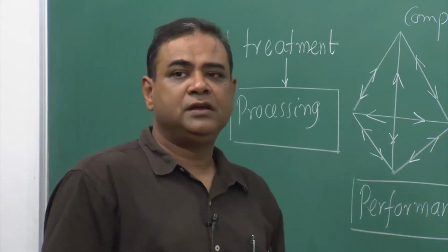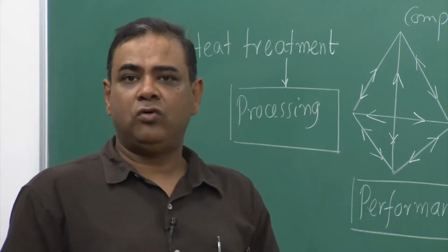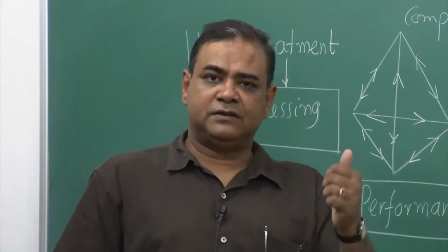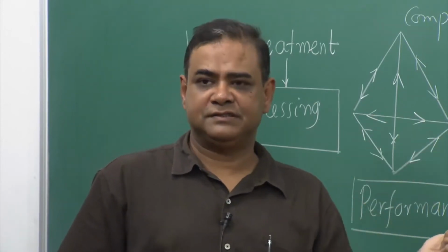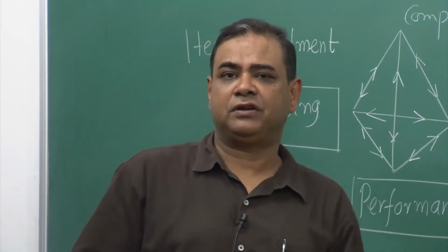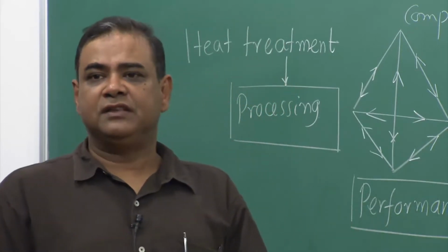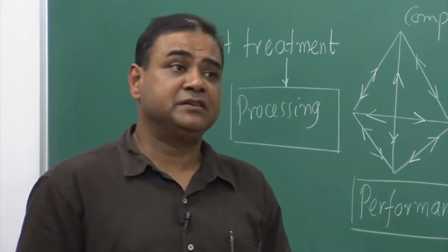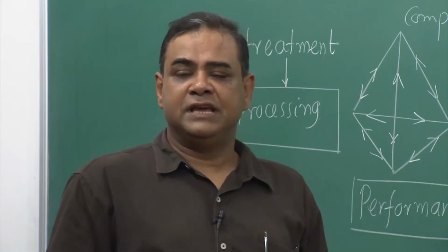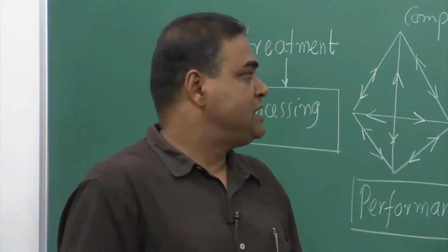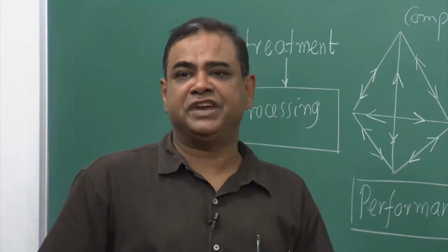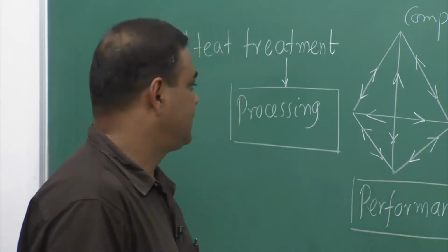And similarly, if we do water quenching or oil quenching after taking it to 1000 degrees Celsius and holding it for 30-40 minutes, we see that the entire structure is changing. There the crystal structure changes, even the microstructure changes, and you see a huge change in the properties.